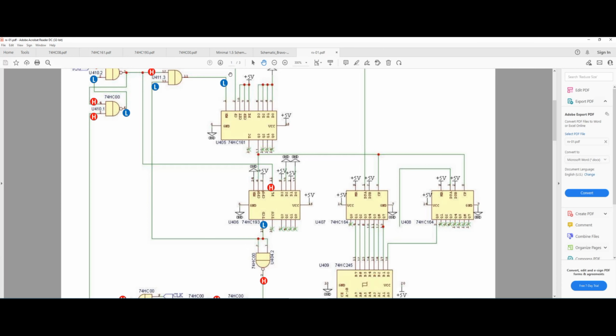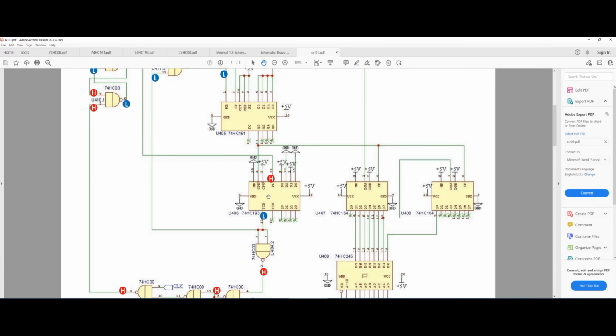We talked about that, right? This is resetting, therefore no clock pulse is coming here. And also, if you look at the CPU, this is the count up pin, which is tied to high because we are not counting up. We're just using the other, the CPD count down pin, to do a countdown.